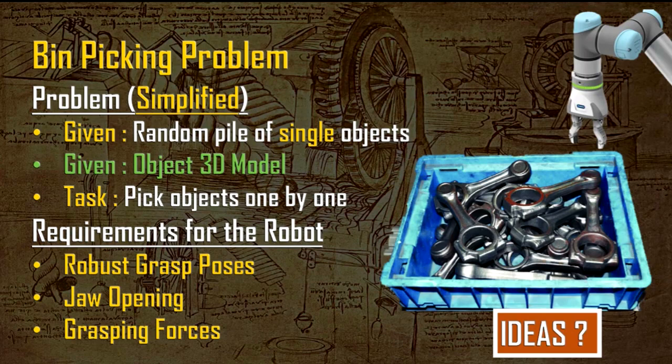At first, we take a picture and we find a couple of ellipses, not circles, ellipses. Then a dedicated system decides to change the angle of the robot in order to capture the full circle. That means that in this position, the robot is exactly at 90 degrees in front of one of the details. It doesn't matter which one.